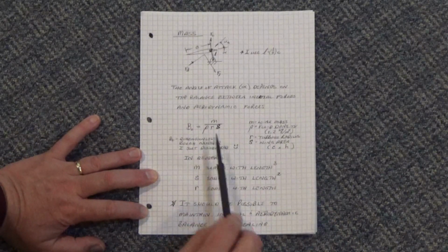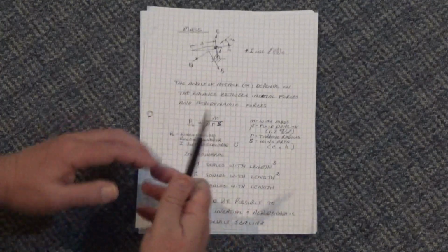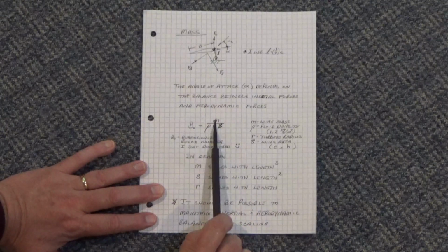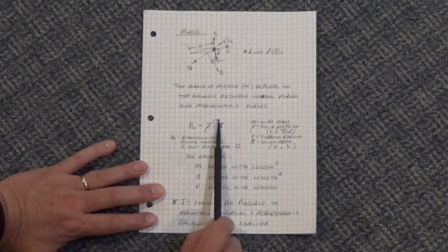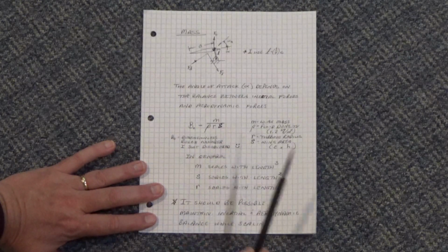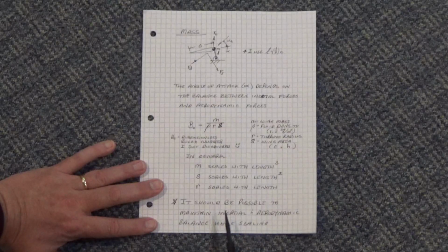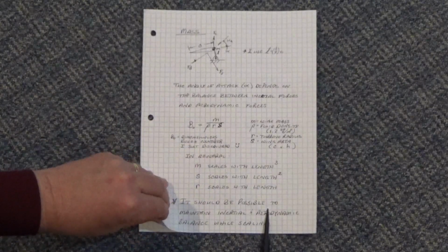But then this R also scales with the length, because if you double it, then the radius of the turbine doubles. And that's nice because what ends up happening is you have length cubed in the numerator and length cubed in the denominator. And so in theory, it should be possible to maintain this balance between inertial forces and aerodynamic forces while you're scaling the turbine up and down.